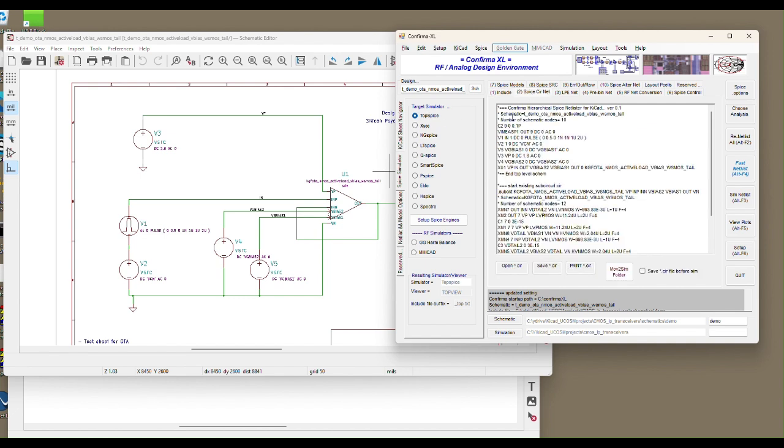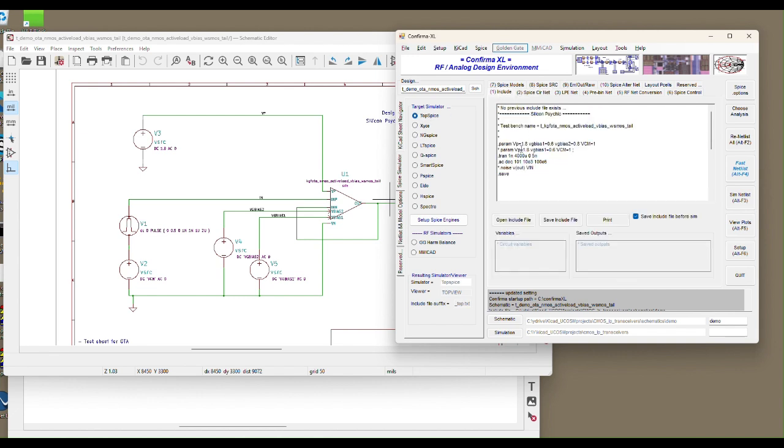But what's important is that the SPICE simulation netlist, the one that comes from the schematics, doesn't change at all. And so what that means is you can still run separate simulators with separate differences in syntax using this methodology, but you can still do all that from the same set of schematics. So you don't have to have specialized schematics targeted to only one simulator or another simulator. You just have one set of schematics, and you can still run those various simulators.